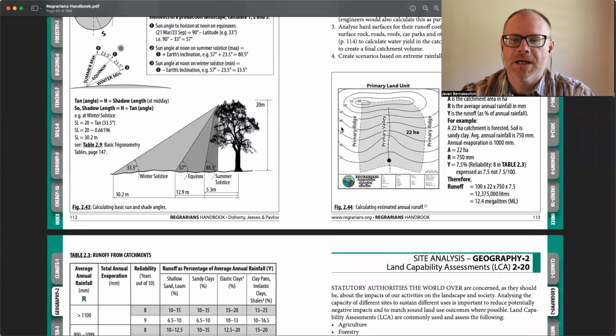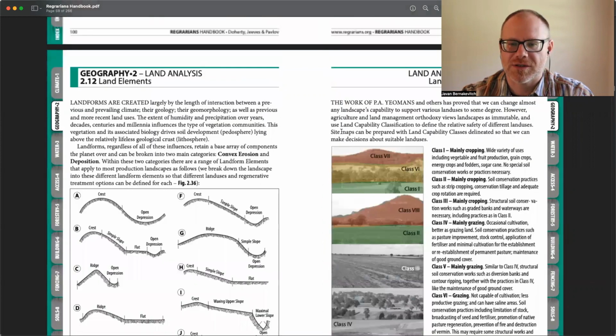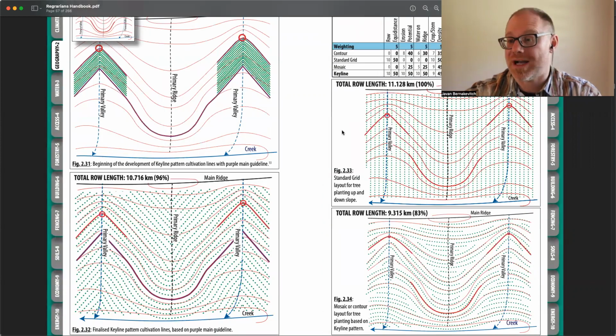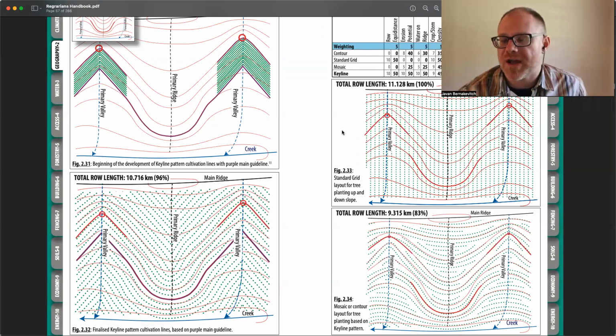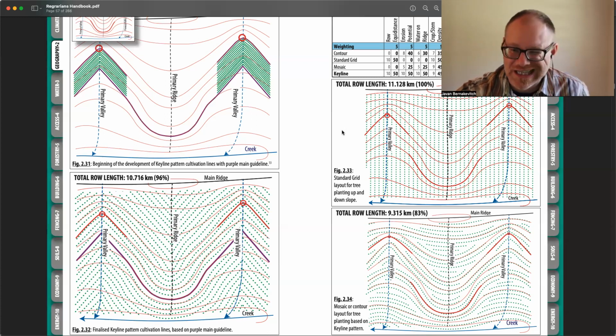So getting back to your question, what's the key point? Why is it of value? And what do we do with it? The key point is the point in a primary valley that goes from convex to concave, the point just after it, the inflection point, where generally soil in solution has a chance to slow down, usually where we have clay layout. And it's usually, if we do end up putting a pond in here, where we'll excavate and get the most amount for our excavation.